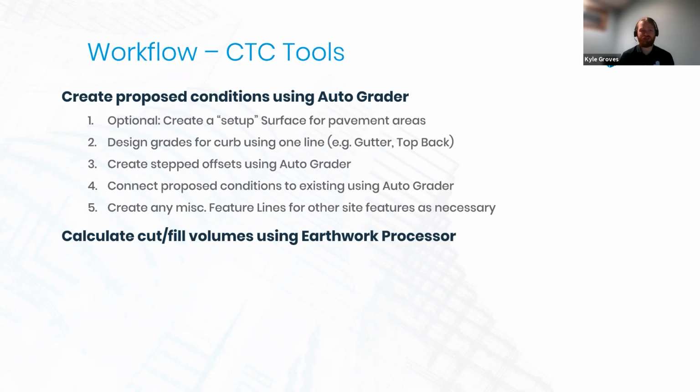And once we're done with that, we can use Earthwork Processor to calculate our cut and our fill volumes. With this, we'll need closed polylines representing those different materials on our site. Maybe it's different existing in situ materials. We've got some sandy soil over here, we've got some clay soil that we need to do some more excavation for. That'll work on our stripping.